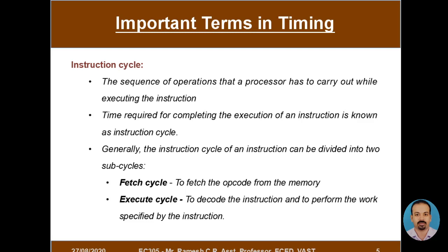In some cases, the entire sequence of operations that has to be performed by the 8085 completes in the fetch cycle alone, the opcode fetch machine cycle alone.